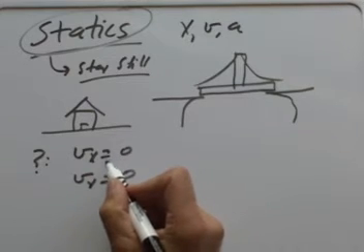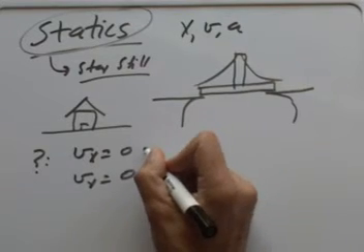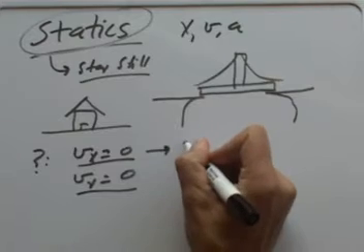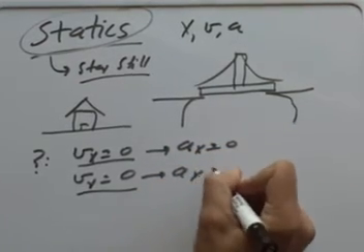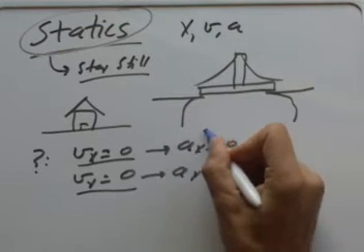So if you can build a thing so that it's already not moving, you just don't give it any velocity. Now, I don't think that's very hard to do. You can just put 2x4s and so on at your job site so that they're not moving. I think that's okay to handle. But the trick then is, once you have it not moving with no velocity, you also want it to not have any acceleration. You want ax to be 0 and you want ay to be equal to 0. Now, this side over here can be the tricky part.